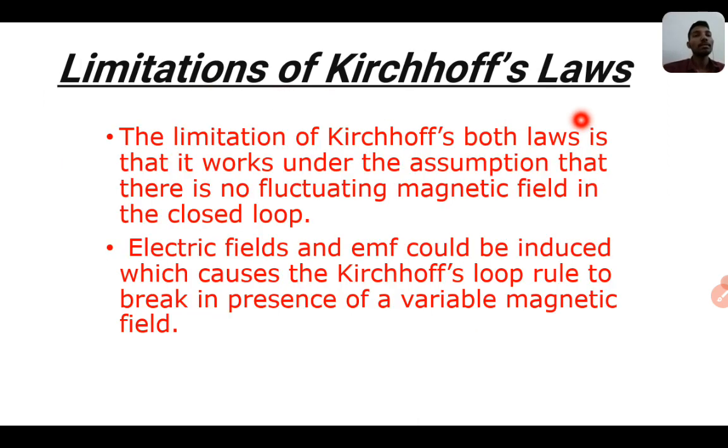Limitations of Kirchhoff's law. The limitation of both laws is that they work under the assumption that there is no fluctuating magnetic field in the closed loop. Electric fields and EMF could be induced, which causes Kirchhoff's loop rule to break in the presence of a variable magnetic field.